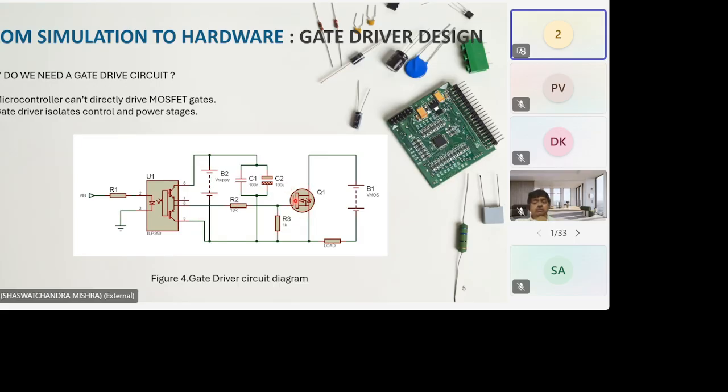During fast switching, we need the gate driver to turn on and turn off faster, right? If we don't have enough current flowing through this gate driver circuit, because if you know about MOSFETs, then the gate terminal circuit inside the MOSFET appears like a capacitor. So if the switching frequency is too high, then the current may not be sufficient to turn on this MOSFET. The voltage across this gate terminal is not sufficient to turn on this MOSFET, right?